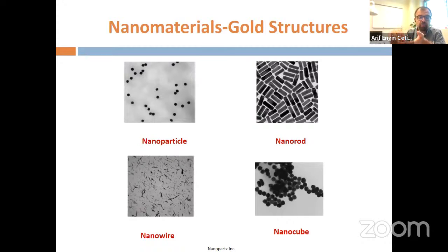For example, aluminum or copper has better optical properties in my applications compared to gold, but I'm still using gold because copper or aluminum can get oxidized in just one day. So its optical properties could be damaged, and also its surface is bad for any attachment of biomolecules. That's why in many applications you see gold as a metal instead of other noble metals.